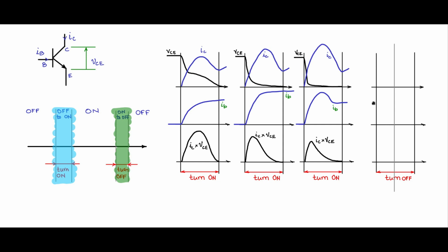So now look at the base current. The base current was at this level, and then I'm going to initiate turn off of the base current. So the base current is turned off. Actually you are removing the base drive, but the base current here then starts going negative, meaning there is some base charge which is removed from the base of the transistor.